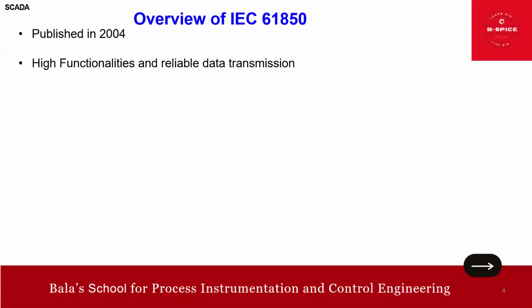So IEC 61850 has not only taken over the drive of the communication technology of the office networking sector, but it also adapted the best possible protocol and configuration for high functionality and reliable data transmission. Then industrial Ethernet, which has been hardened for substation purposes and provides a speed of 100 megabit per second, offers bandwidth enough to ensure reliable information exchange between IEDs, intelligent electronic devices, and a substation controller.